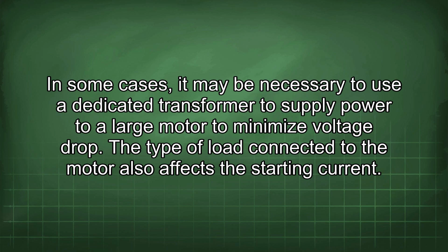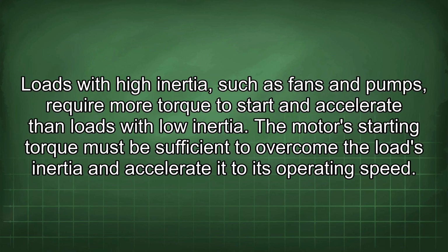In some cases, it may be necessary to use a dedicated transformer to supply power to a large motor to minimize voltage drop. The type of load connected to the motor also affects the starting current. Loads with high inertia, such as fans and pumps, require more torque to start and accelerate than loads with low inertia.